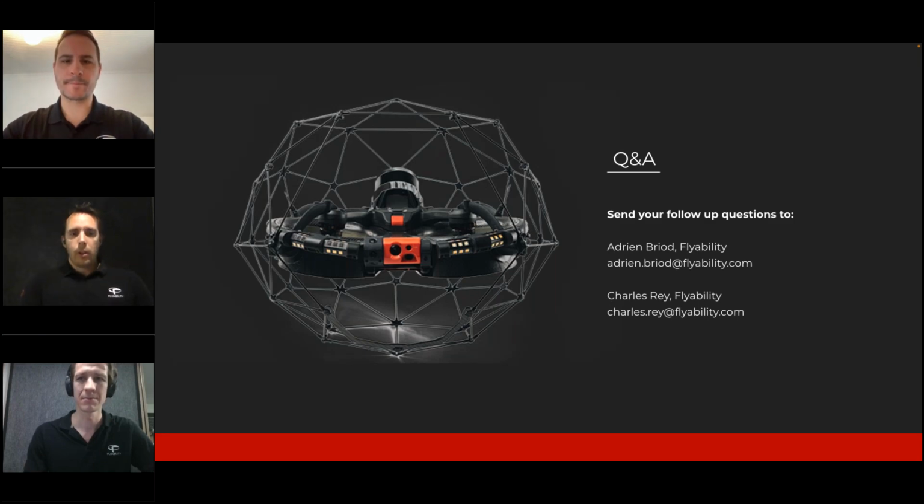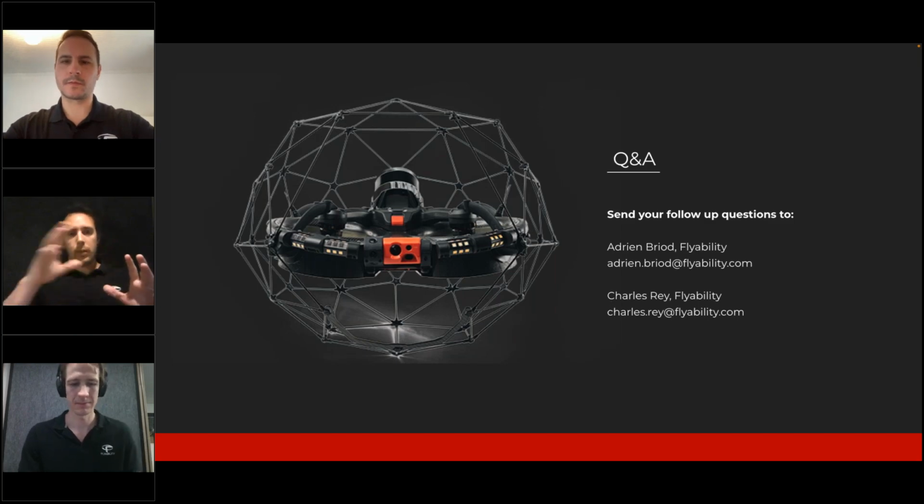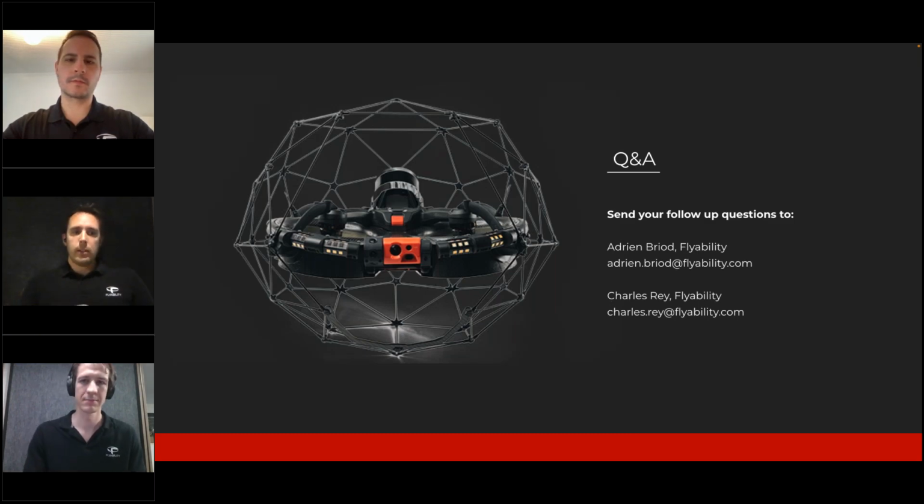No, for the complete processing, if you want to have a high accuracy map, you do your flight, you post-process your flight in GeoSLAM Connect, and then you can use other software to do volumetric measurements. If the accuracy is not very important, you can potentially use the live map. We did it on a small stockpile, and the results were not too bad, but it's not done in FlyAware, it's done in other software like CloudCompare.